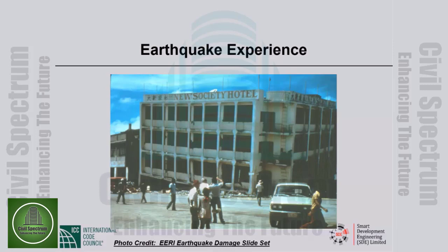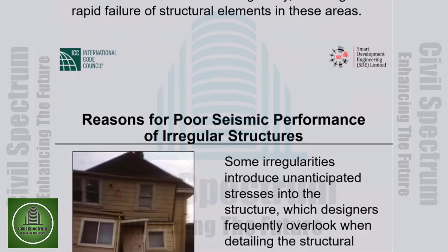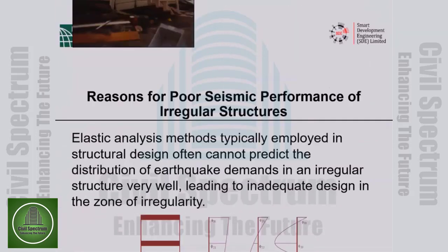That goes without saying. And when the shear walls begin to yield, the loads transfer from those yielding elements to the frames. And you will not capture that out of an elastic analysis. There is no way. Okay, so that's what we are trying to say on the slides that I was on.